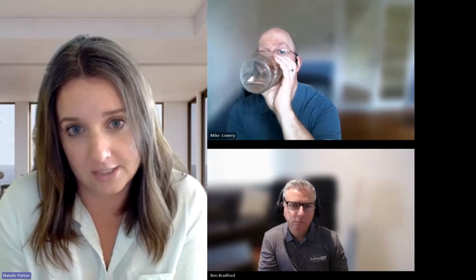So an analytic that's triggered at one point in time might come in as a low priority based on its severity within that equipment itself, its impact on the operation of that equipment. But the priority calculates based, in part, on the duration that the issue has persisted. So when that issue is first identified, it's a low priority. But if it's not addressed, the impact may compound over time. And so in 3 days, if it has still been happening for that total duration of 3 days, then the priority is going to bump up.